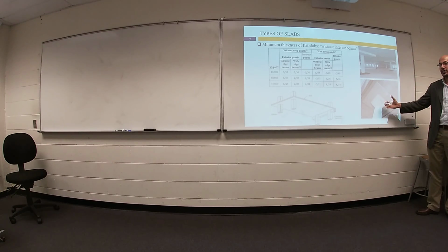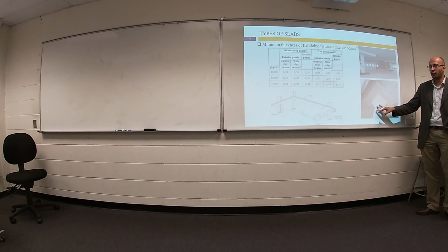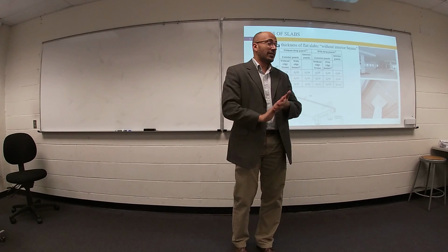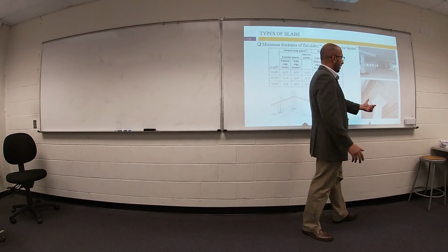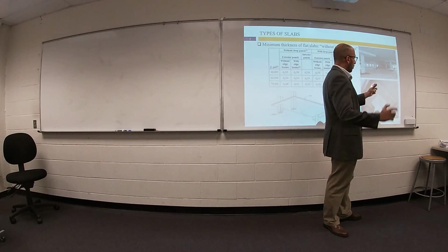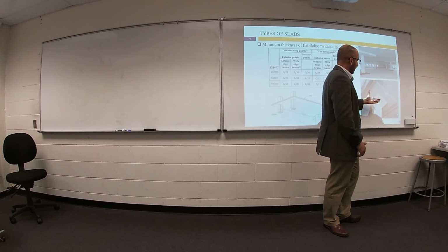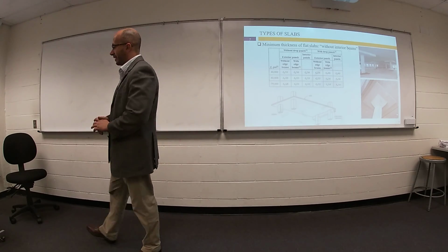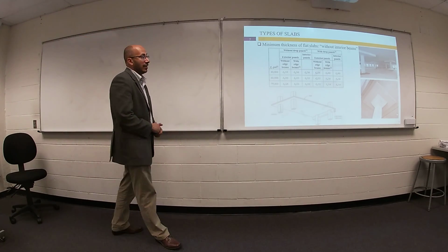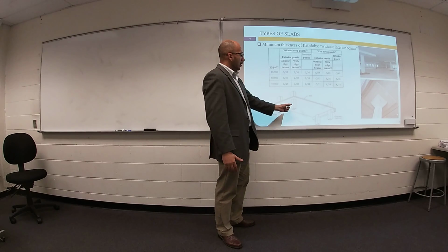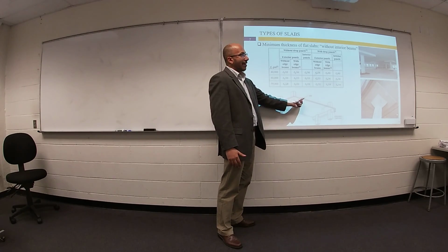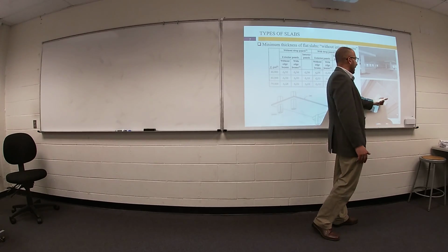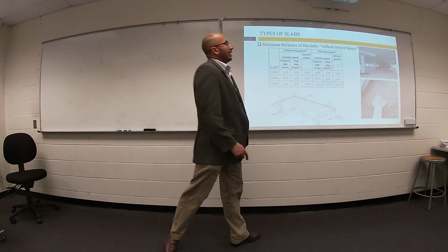So if your shear, if your punching is still unsafe, change your main system and choose something else, because there is nothing after this. You have the head of your column, you have the drop panel, and you have your original slab, and your shear, your punching is still unsafe, so we need to change the statical system. Select something else. The original shape of your flat slab is a column supported by slab directly. Sometimes we have drop panels, sometimes we have drop panel and column head. Anyway.